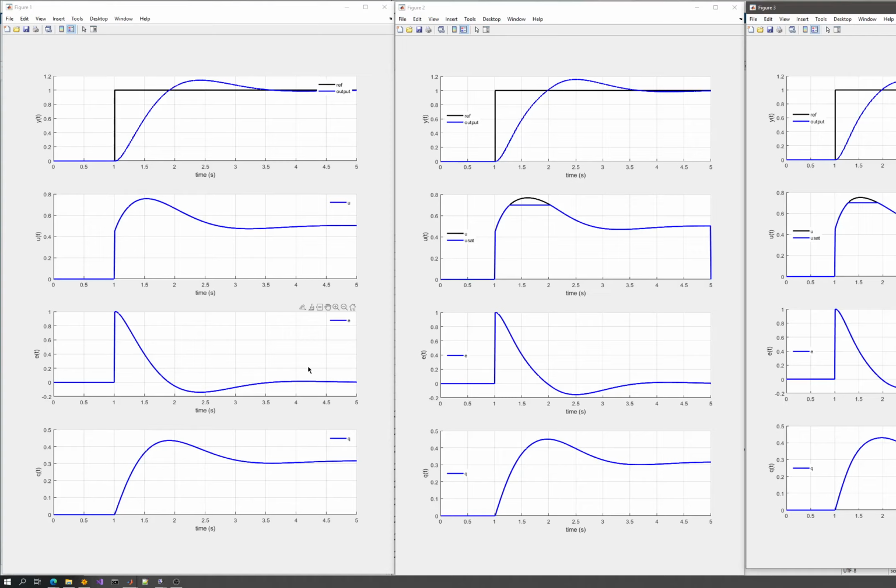or almost best solution there. So what this lesson basically tells you is that integrators are very necessary, but they have a drawback if you have saturation. And control signals tell much about the system, because if you look at the output and the internal signals, you might be evaluating more than you think, because they have more information than most of us think. And u(t), the control signal, is very important, because if you are in a control system that needs to, let's say, have a power saving mode, this means that you will look at the control signal and the energy.